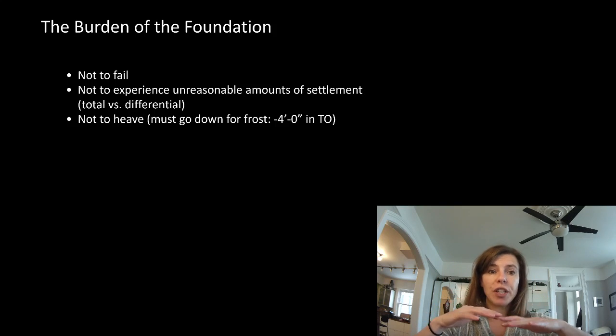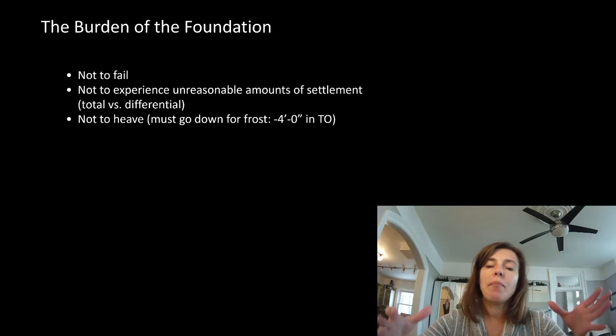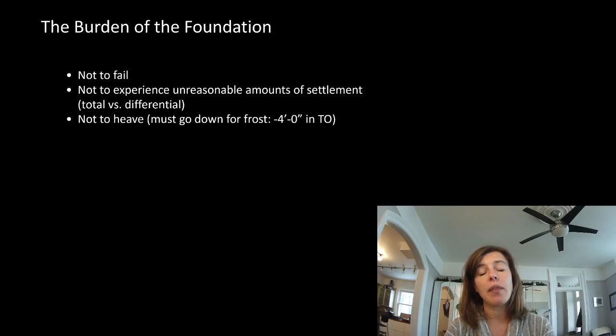You can imagine if you've ever walked along the beach, for example, on a day where there's big surf, you could walk on the dry sand or the hard packed sand or the wet sand, and if you plopped a building there, you could imagine that it would react to the loads differently in each spot, and that happens in real life with a building. So there are 2 criteria we design to: the total settlement and differential settlement.